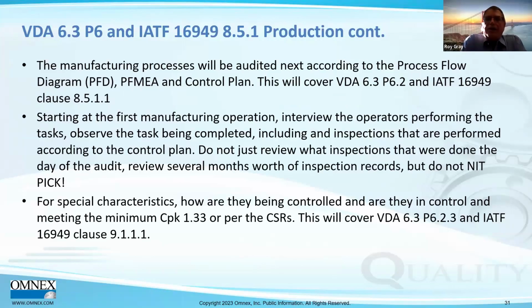Manufacturing processes audited. Follow the process flow diagram, PFMEA, and control plans, and make sure all the processes are identified. When you do this in VDA 6.3, you're actually in P6.2, and then IATF 16949, clause 8.5.1.1.